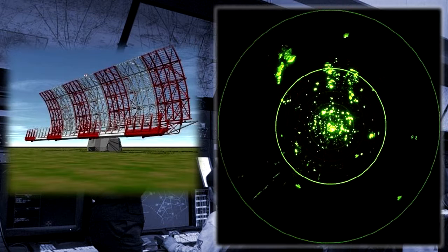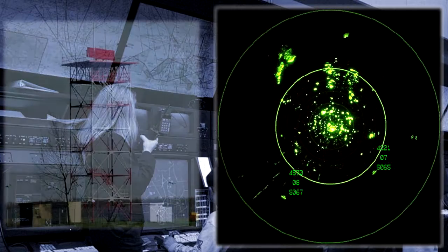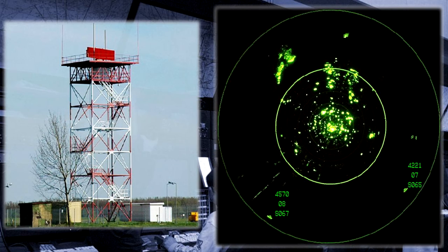Primary surveillance radar emits pulses of energy, some of which is reflected by the target back to the receiver. These targets can be objects other than aircraft. The radar return information is then processed and displayed on a screen, like the one shown. Secondary surveillance radar requires that the target aircraft have equipment on board to reply to signals sent from the base unit. These signals give more data to the radar return, like aircraft identification, altitude, and so on. Secondary surveillance radar is dealt with in more detail in another lesson.